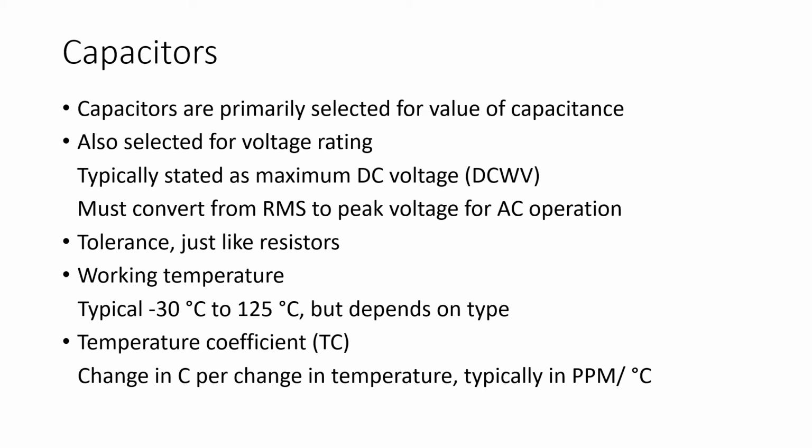And with capacitors, we're also concerned about the temperature coefficient, and this gives us the change in capacitance per or by a change in temperature. And typically the temperature coefficient is expressed in parts per million per degree Celsius.